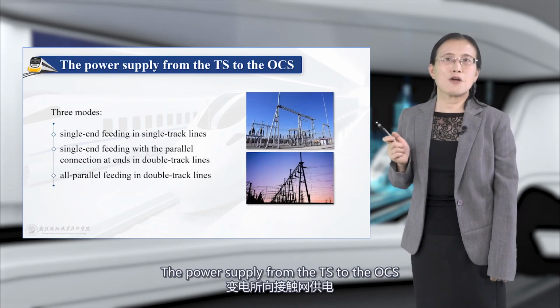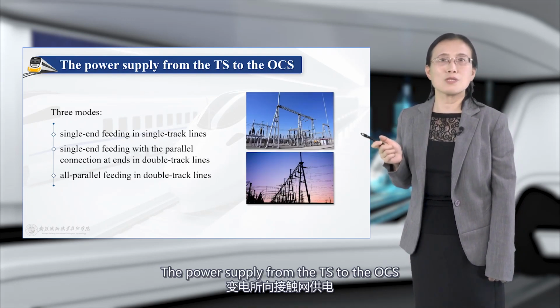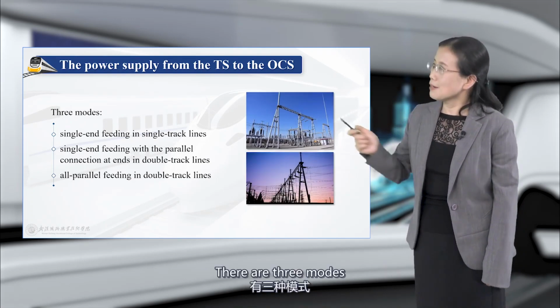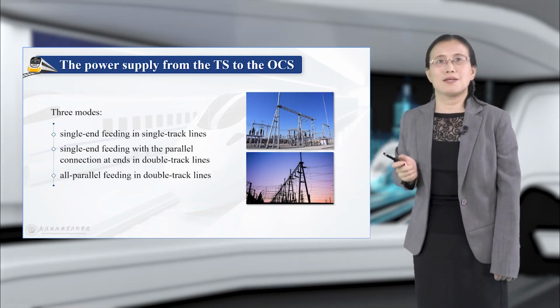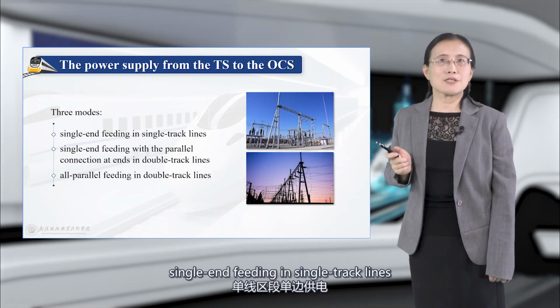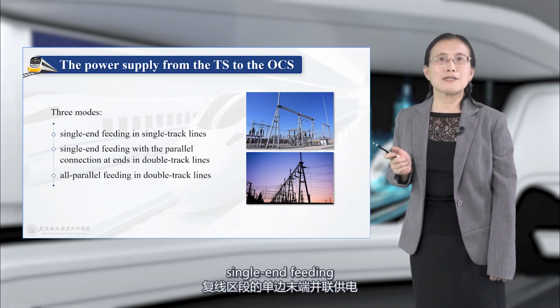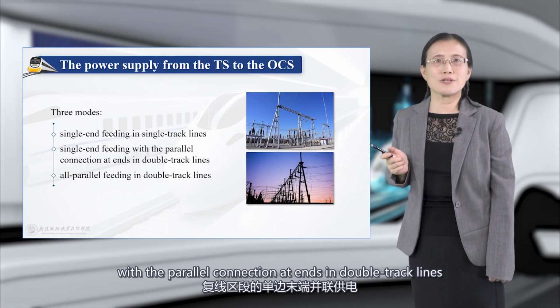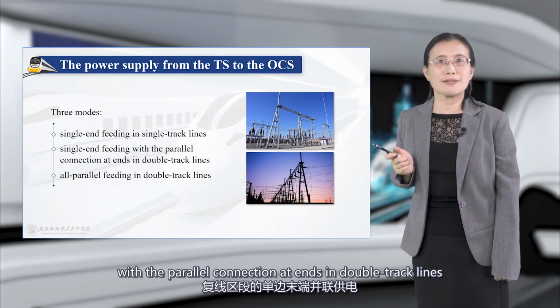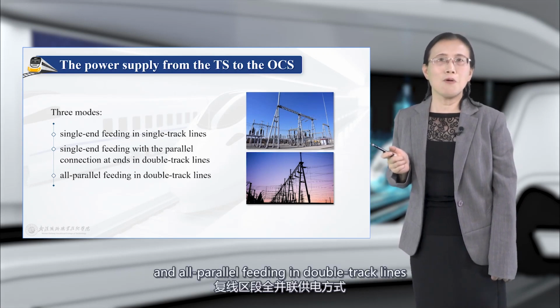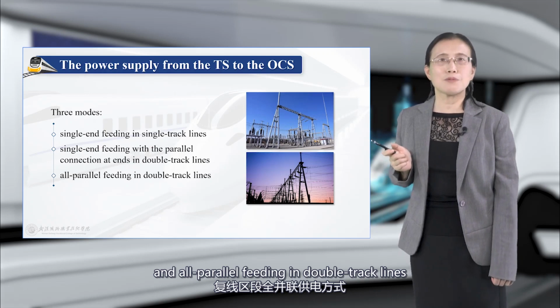The power supply from the TS to the OCS. There are three modes: single-end feeding in single-track lines, single-end feeding with the parallel connection at ends in double-track lines, and all parallel feeding in double-track lines.